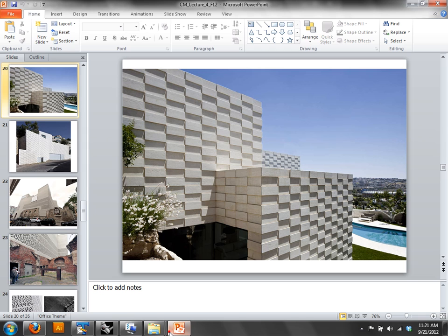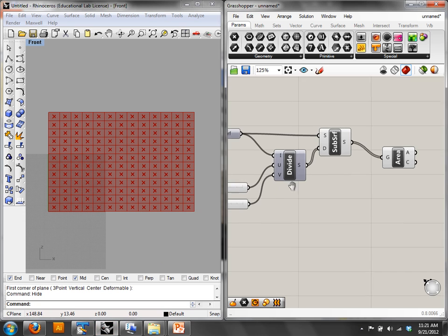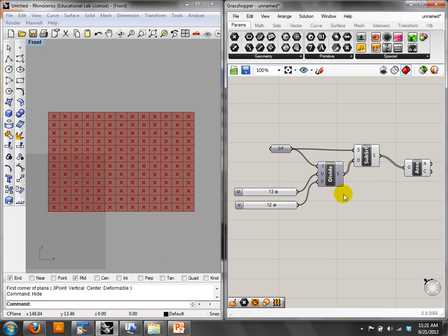And so that can be a place for you to distribute geometry in your projects. Okay, with this particular project, I just showed you something, right? With extrude, I can extrude those panels out basically. I can take the surfaces that I cut the thing into, and I can extrude every other one. Okay, and so that's actually what I'm gonna do here. So this is one example, and the advantage of starting with the surface is that if the design is based on this, then if I change the surface, the design changes.